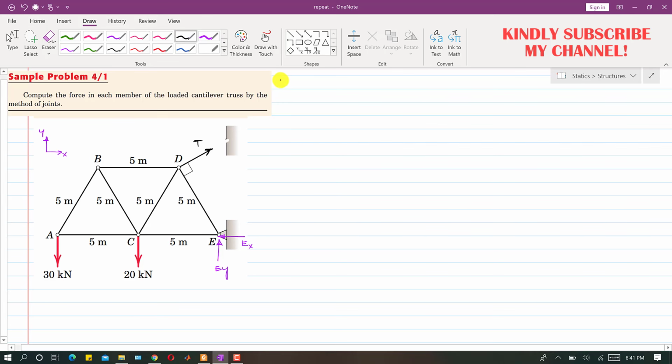Now if I apply the summation of moment at point E equals 0, then Ex and Ey are not producing a moment about this point E, so we can find this T. If we assume that the counterclockwise moment is positive, the 30 kilonewton force is producing counterclockwise moment about point E, and the 20 kilonewton force is also producing counterclockwise moment, and T is producing clockwise moment. So I write minus T, and the perpendicular distance of T from E is this 5 meter, perpendicular with this member.